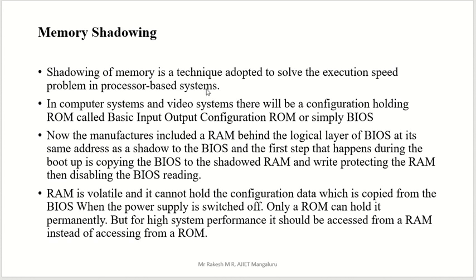But if you place that BIOS code in RAM, it will be erased once you switch off your device. So we keep all those codes in the ROM, in the separate BIOS part. After you switch on your device, we take that BIOS code into RAM, execute it, and after that keep it back in ROM itself.